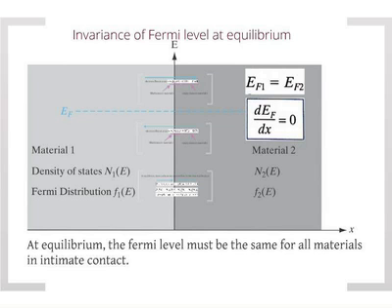We're going to change gears a little bit and come to another important phenomenon. Essentially, what happens to the Fermi level at equilibrium when you have carrier concentrations of different kinds? This is actually quite important later on when we talk about p-n junctions and so on. And this is very general, basically almost like a theorem that you can apply in a variety of situations, okay?